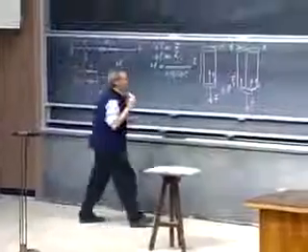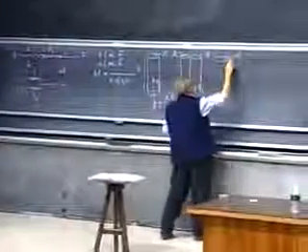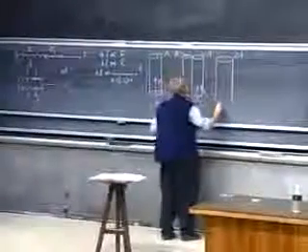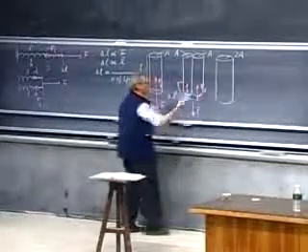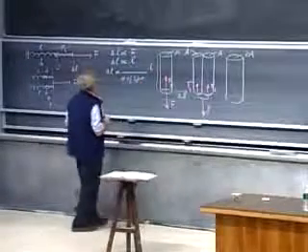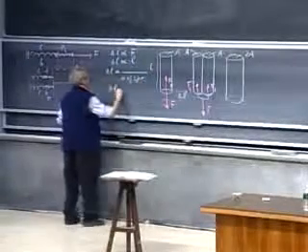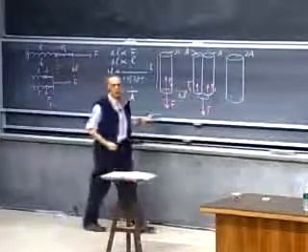And so now we have a situation that if I made a rod whereby this was 2A, just one rod, which is completely equivalent to this situation, I'm only getting half delta L for a given force. And so now we have that delta L is inversely proportional to the cross-sectional area of the rod.